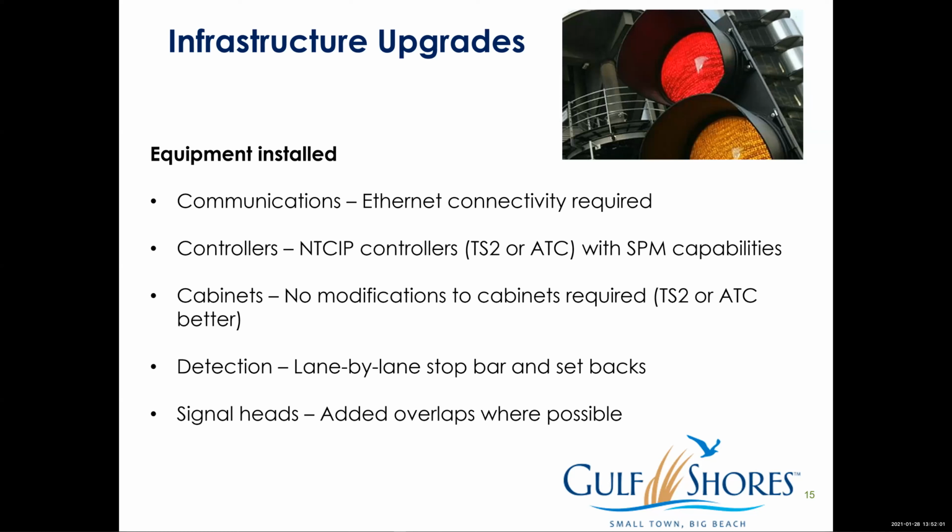That way we can do lane by lane detection at the stop bar and get the setbacks on a lane by lane basis as well. Signal heads, the only thing we did on this system was add overlaps where possible. The addition of overlaps really helped move traffic a little bit better and gave us an increase in efficiency.